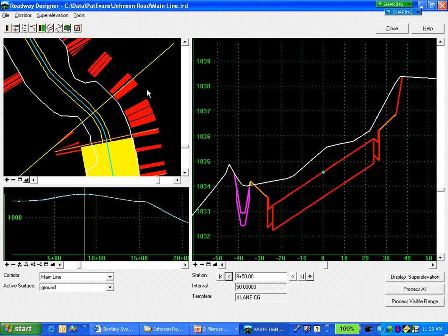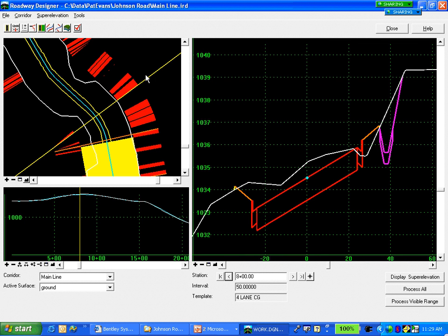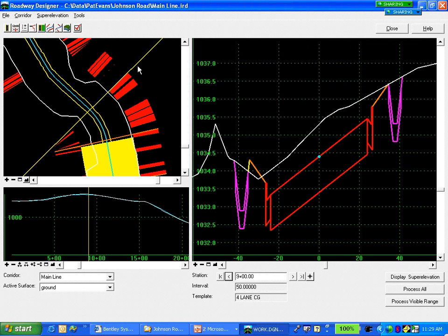So it gives you the ability to come in here and say, okay, look, I've got a ditch here. I don't have a ditch, I don't have a ditch, I do have a ditch. So, these are things that you would want to be aware of. Maybe there's a driveway there or something, so you need it like that. But maybe there's a condition on the ends that you need to come in and do an end condition exception. And this is going to happen just about any time you're doing a design. So that's just something I wanted to point out for you in our roadway designer there.